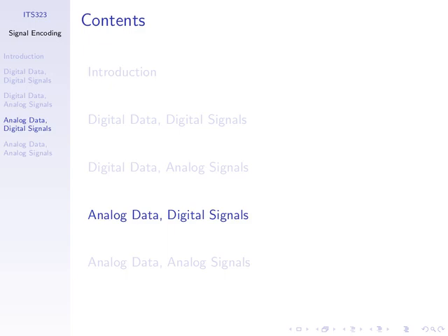What we know is that we've gone through the first two approaches. If we have bits, digital data, and I want to send digital signals, then I simply map the bits into one of the different pulses. That is, bit 0, high voltage, bit 1, low voltage. But it can be more complex than that, and we saw the different encoding schemes: non-return to 0, bipolar AMI, Manchester, and there are others. So they are encoding schemes if we have digital data and we need to transmit digital signals.